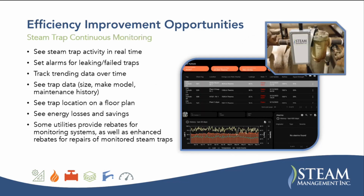Speaking of monitoring, here is an example of a monitoring dashboard. This is a trap monitor. You see it's just clamped on downstream of the steam trap. This is an ultrasound-based monitor. There are different types of monitors which can be implemented for different situations, but generally they're going to show you your whole trap population, or at least the monitored trap population, on a dashboard, and you're going to be able to trend the trap function over time and see failed traps.